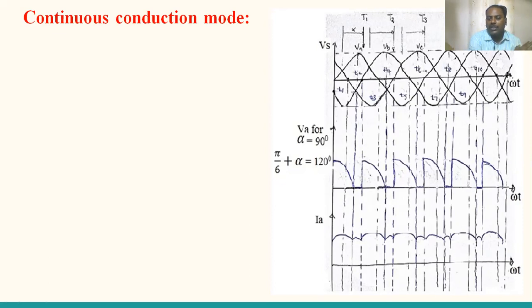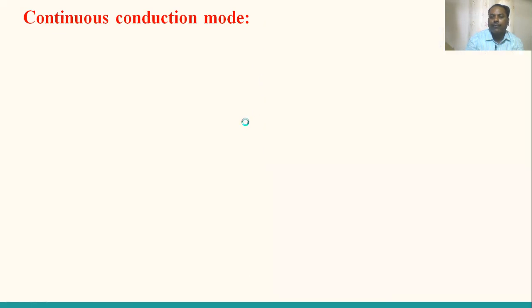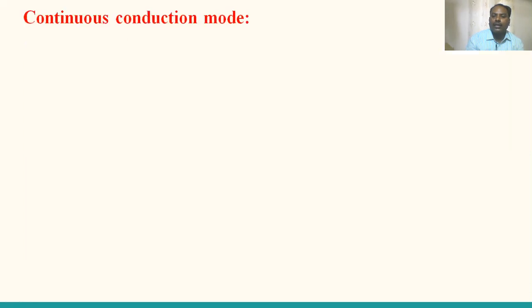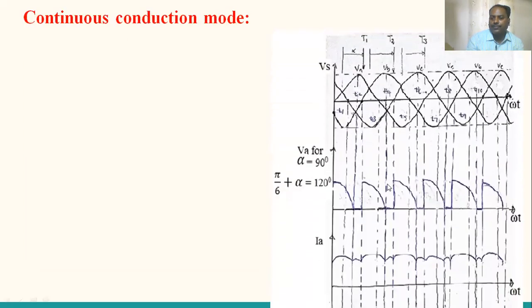Therefore, there is no power transfer from source to the load. At that time, the motor is already connected to an active load and is in running condition, so the motor freewheels through the freewheeling diode. No switch is in conduction mode, so the motor terminals are shorted through the freewheeling diode, resulting in the voltage across the armature being equal to 0.